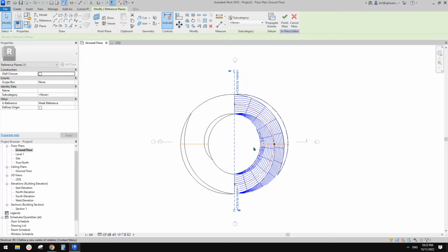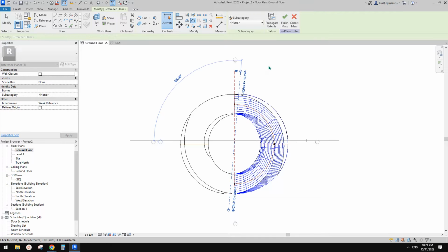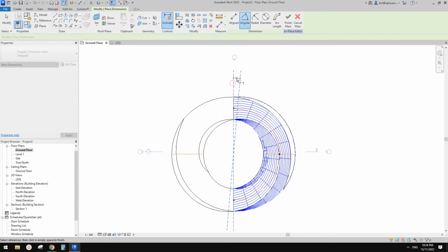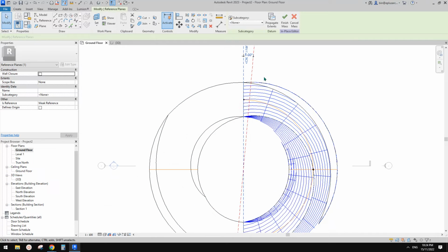So then I'll just rotate, RO, and I'm going to pick the center point. So space, which is place center of rotation, and I'll use SC again. So pick this center point, and then just make sure you have this copy checked. Okay, and then I'm going to maybe rotate it by 5 degrees, which means I'll copy this and the angle between these two will be 5 degrees. Okay, so now we have this one, and we don't need to rotate anymore.